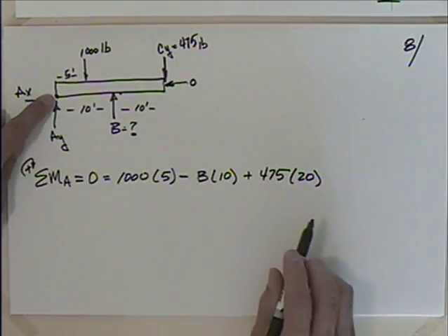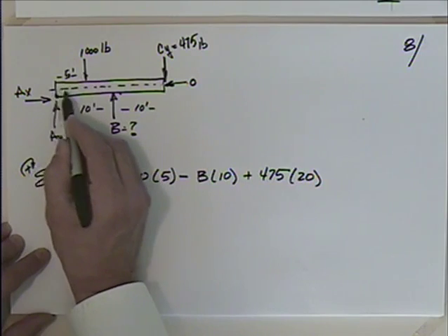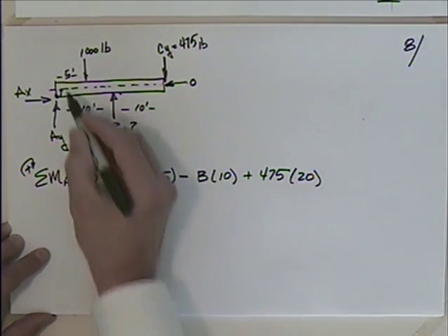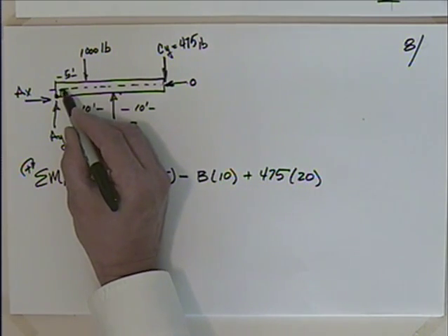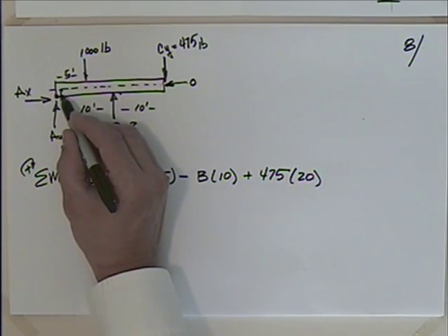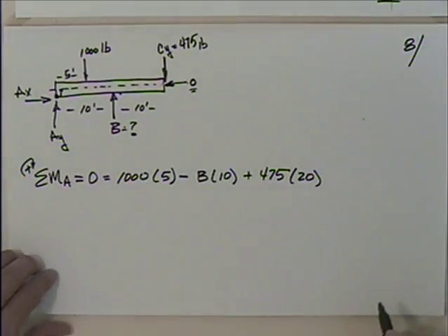This one then intersects it. And a lot of times we would call that distance negligible in there, whether we're summing it about the bottom of the beam or the middle of the beam, unless we're told otherwise. If they give us the dimension, then they're looking for us to deal with that. The dimension has not been given, so we'd have to assume that it's negligible. It's a moot issue, though, because that's 0.